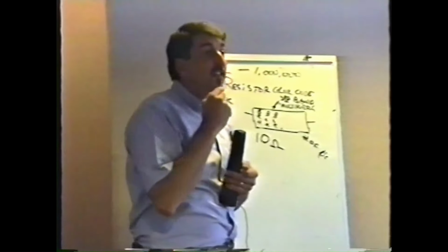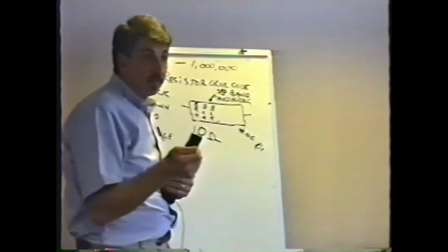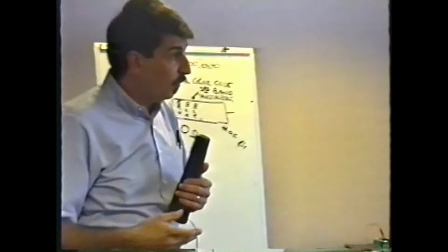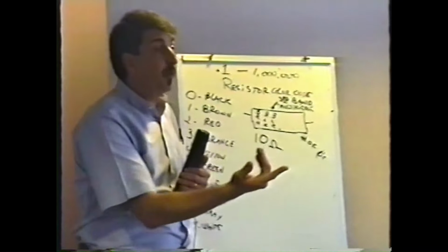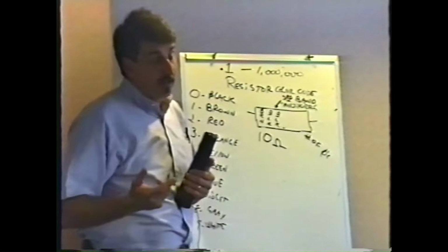It's supposed to be 100 ohms. It's only 10 ohms. So you go over to Radio Shack, and you get a 100 ohm resistor to put in there. You may not notice that the colors are different. It'd be brown, black, brown, wouldn't it? If it was 100 ohms, it'd be brown, black, brown. So you replace that 10 ohm resistor with the 100 ohm resistor. Obviously, when you turn the thing back on, it doesn't fix anything, does it? Because you not only changed a good part, but you've replaced it with a part that's the wrong value, right? You made it worse, because even if you eventually find which part is actually bad, you may never get it to work because this new resistor you put in there is 10 times the value it should be.